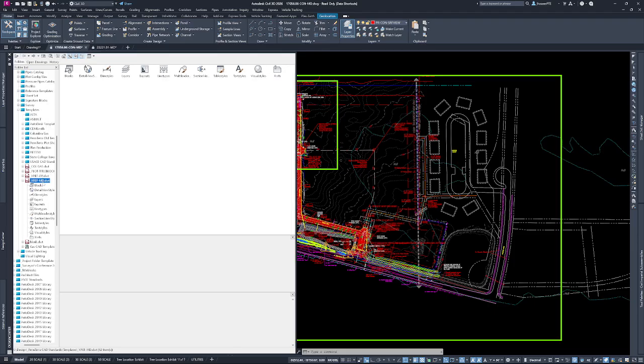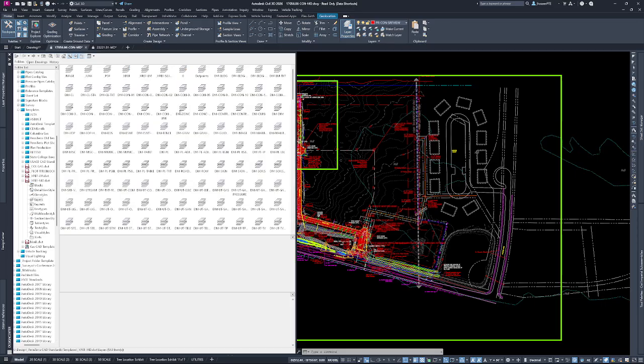So right now, this is the template file. I know if I need information, I might have had a demo layer that I purged out, but now I need a demo of something that was on that layer. Instead of having to recreate that layer, make sure everything is correct with the naming, the layer type, line type, and color, I can actually just go into my Design Center, go to my template, go to layers, and it shows every single layer that is in the template.